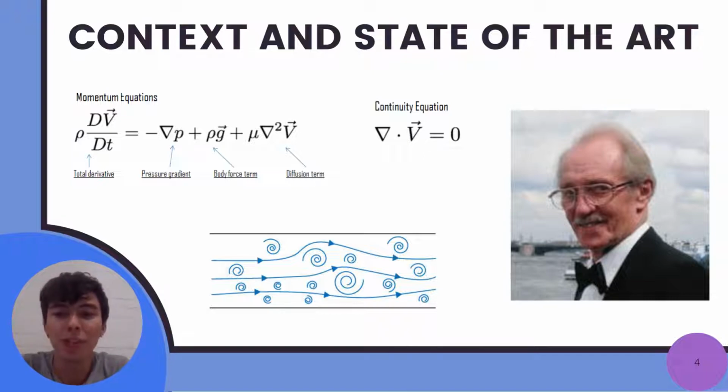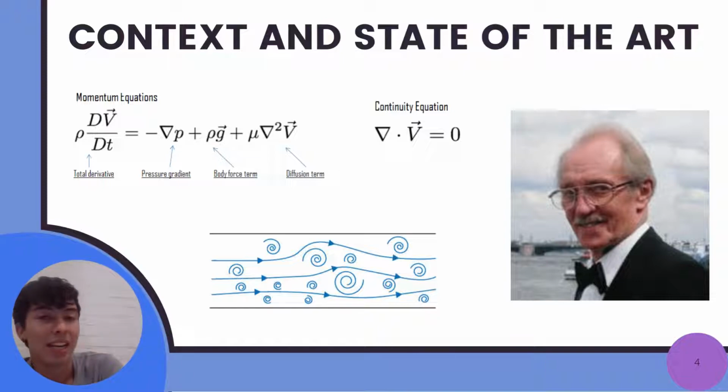First of all, it's important to mention that equations of state such as Navier-Stokes describe the conservation of momentum, which has made it possible to build airplanes, cars, and turbomachines. This is because they describe the behavior of fluids according to their properties and conditions like density, viscosity, temperature, and pressure. Furthermore, CFD consists in applying methods such as the Reynolds-averaged Navier-Stokes that allows modeling turbulence in a suitable way on steady-state fluids, with the respective assumptions such as K-epsilon turbulence, constant density, three-dimensional flow, among others.